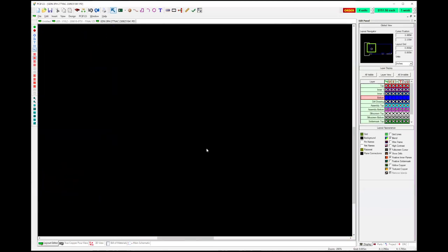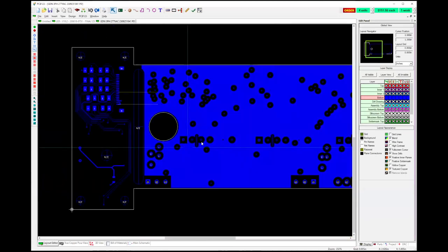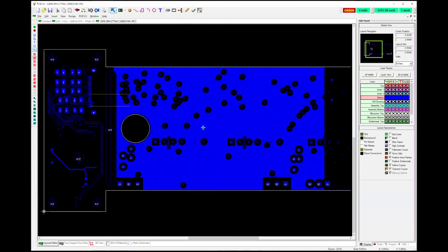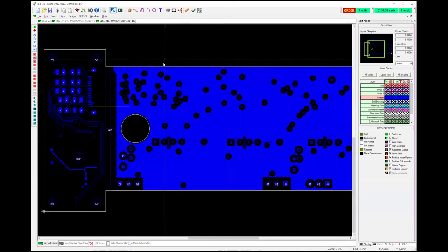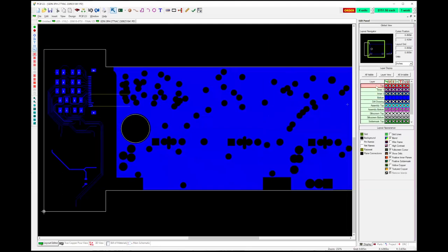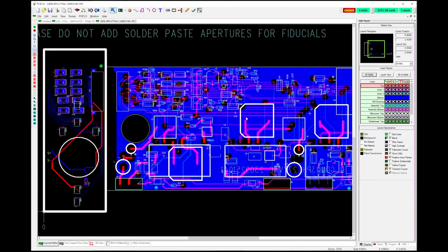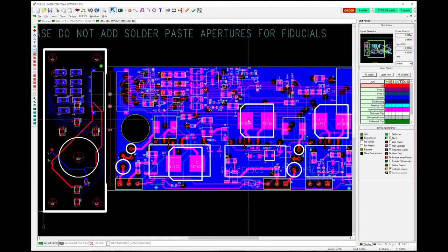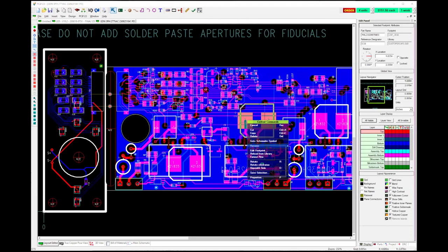What I can do is go in and, if nobody minds, show you how to make a footprint. It's really pretty simple. I always start with a part that's already there. Let's say I want a surface mount electrolytic capacitor. I've got one here, so I know that shape is kind of what I want, but I want it to be smaller and have smaller pads.